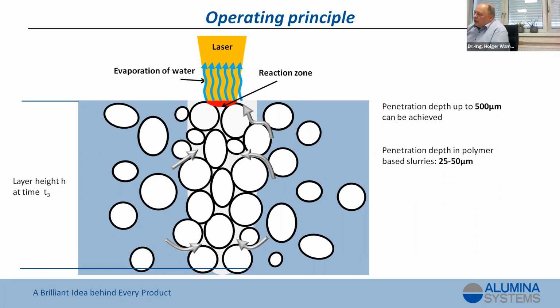What we have not taken into consideration right now is the sintering process as well. We have standard processes for wall thicknesses up to 20 millimeters, and for even thicker parts, up to 40 or 50 millimeters, which we have already produced, we have sintering programs that are twice as long as the standard processes.